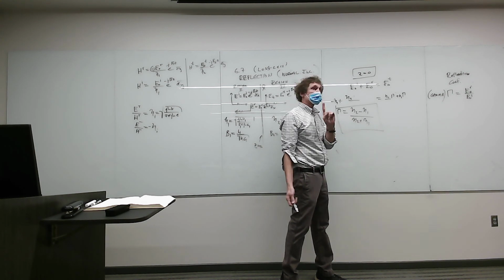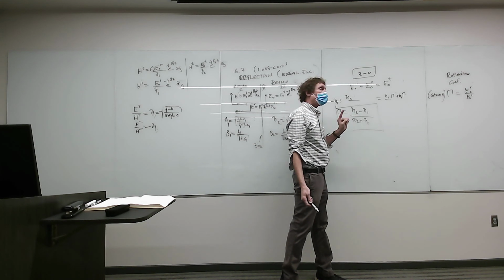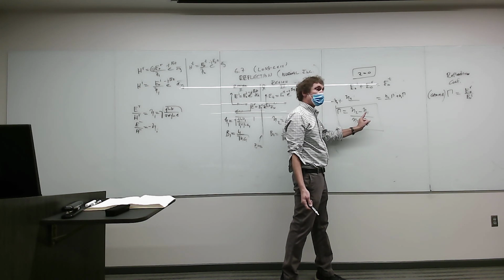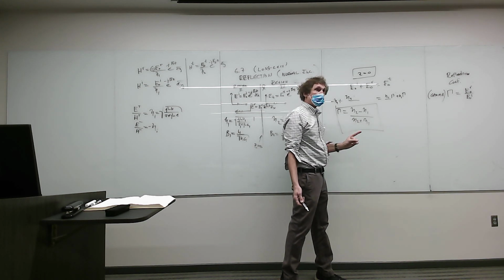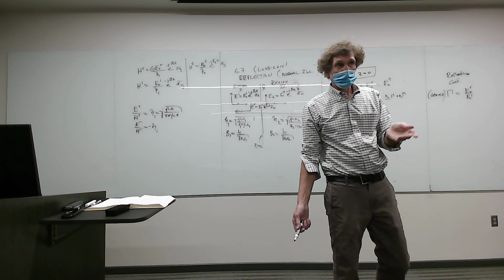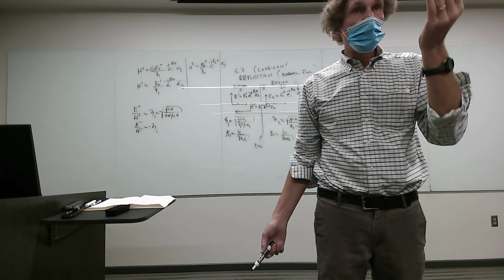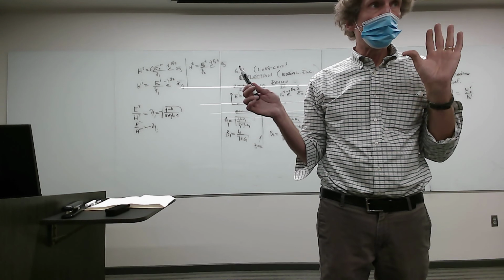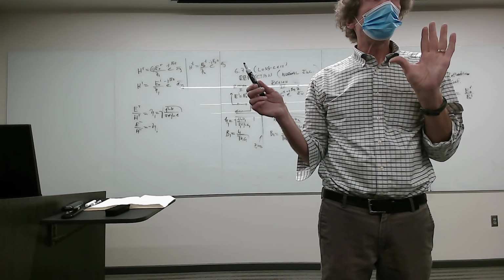It would be plus 1. Do y'all follow me? All right, what about when η1 is much, much greater than η2? Then you would get negative 1. You all see this? Those are the extremes in the value. The reflection coefficient can be 1 or minus 1 at the extreme. As far as the polarity, the magnitude can be 1.